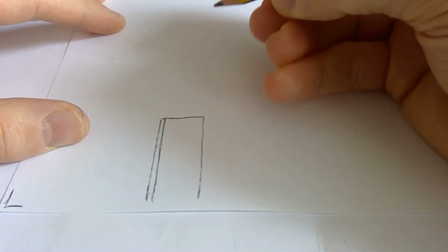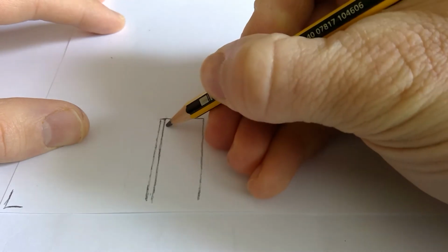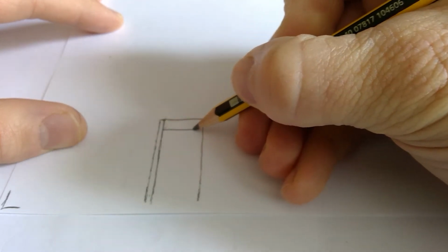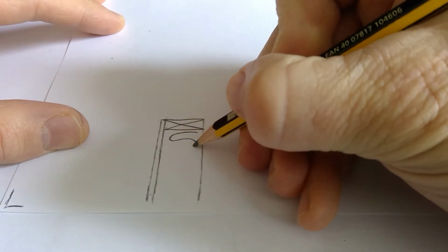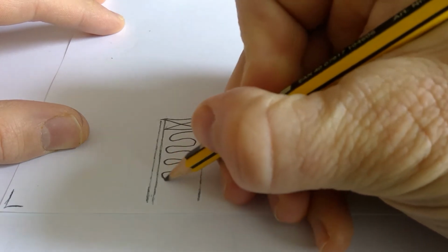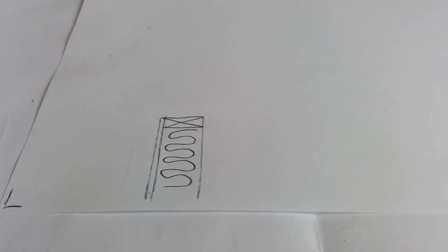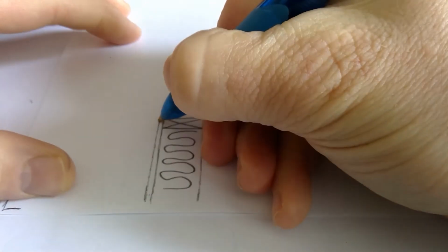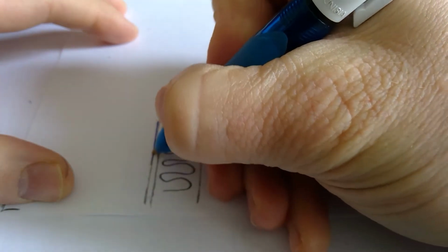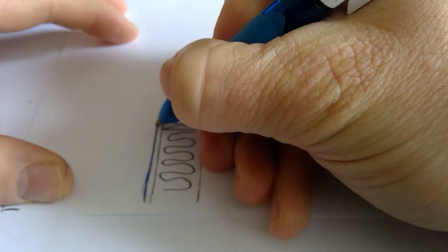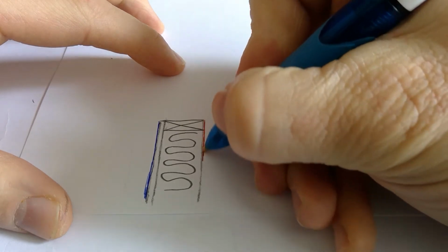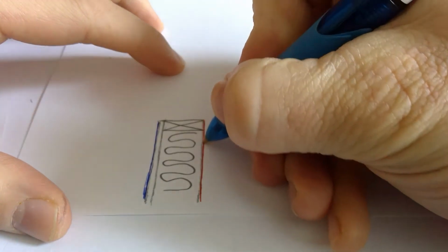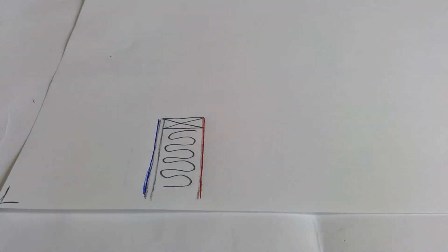On the outside of the timber frame panel, we have OSB wood or plywood. On the top of the timber frame panel, we have just the head plate. And we have insulation inside the panel there. On the very outside of the timber frame panel, we have breather membrane, which allows any moisture in the plywood to pass out through. And on the inside of the timber frame panel, we have an air tightness layer here.